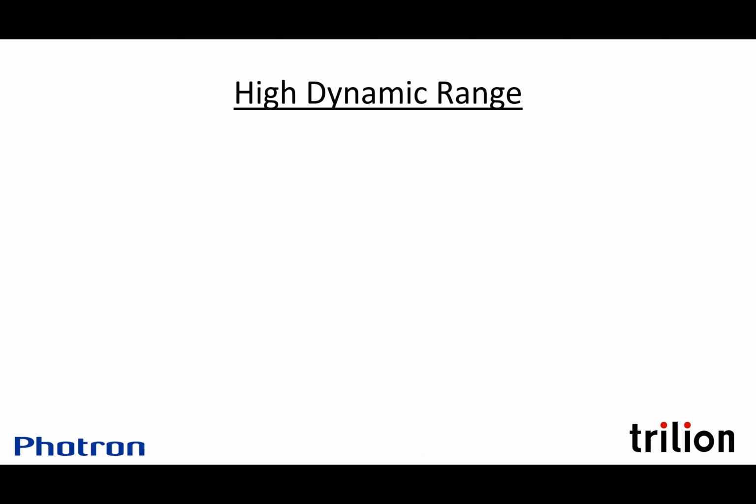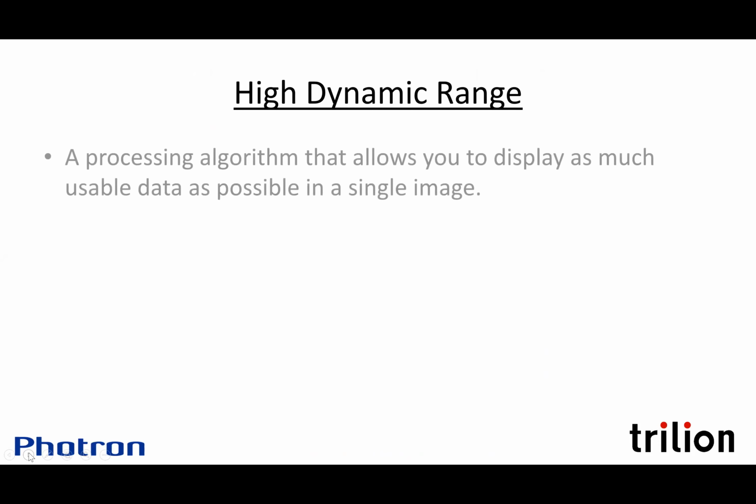On these outdoor kinds of tests, you get into issues with sun shadow and just widely varying and sometimes hard to control illumination levels. And again, there's a feature in the Photron cameras that helps with that kind of negative influence during outdoor testing. Right, and this is where we get into having 12 bits of image data, but only being able to see 8 bits on your computer screen. Just remember that there's always more data in your image than you're seeing on your screen. And one of the ways that we address that is with what we call high dynamic range, or HDR.